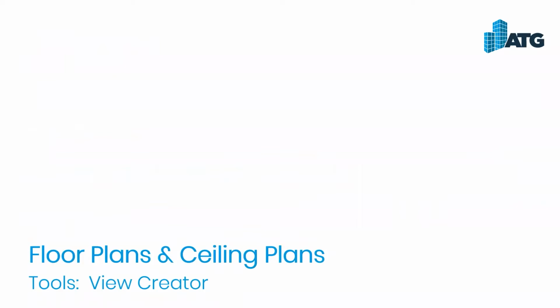Okay, so first let's create floor plans that align with the levels in our building. We want to make several floor plans per level: one for annotation, one for dimensions, a furniture plan, and a life safety plan. In addition, let's assume the floor plate is too large to fit on a sheet, thus we will need partial floor plans for each of these views as well.